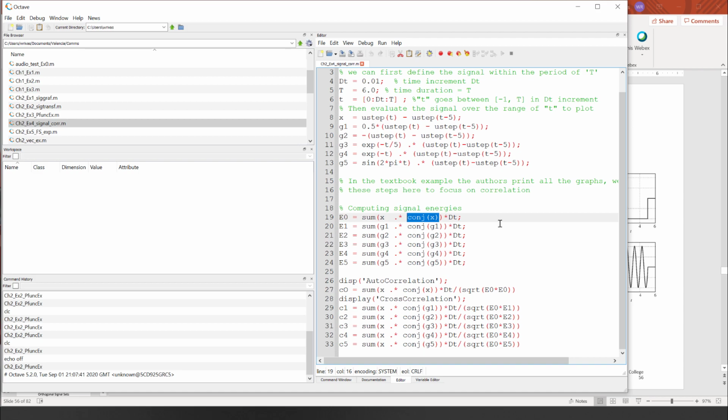And then the first term, whenever you look for the correlation between a signal with itself, we call that the autocorrelation instead of the cross correlation, because it's a signal with itself. And there's reasons to do that. When you do the correlation of a signal with itself, you know you're going to get rho equal 1, but you also get the delay. So if there's a delay between the signal and where you're measuring the signal, you can figure it out with the autocorrelation in general terms.